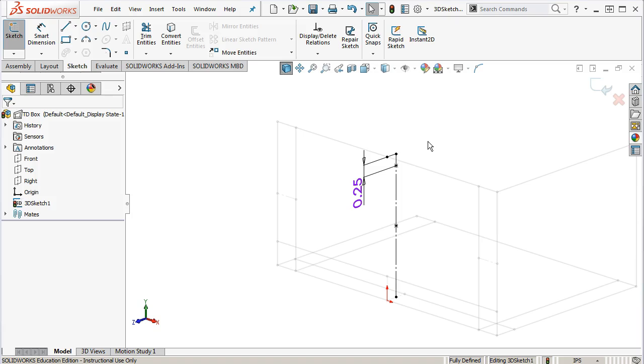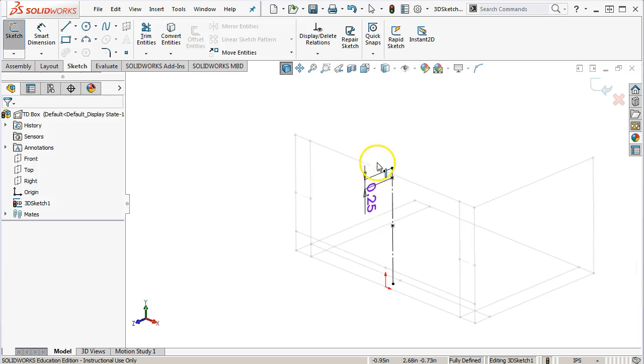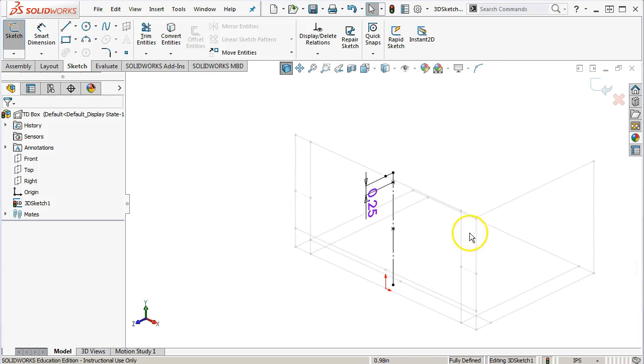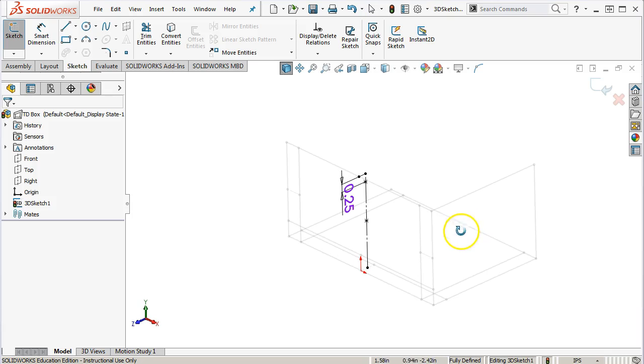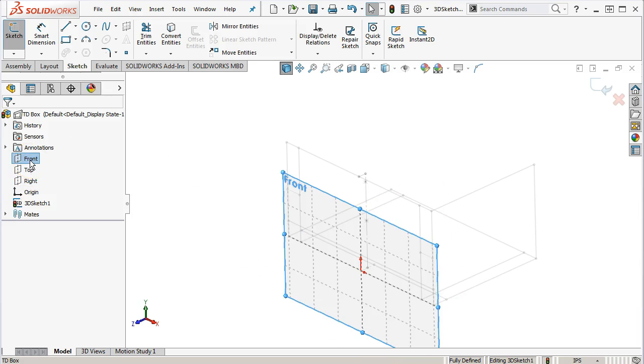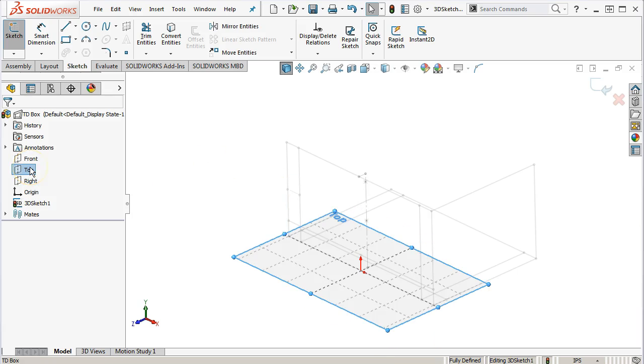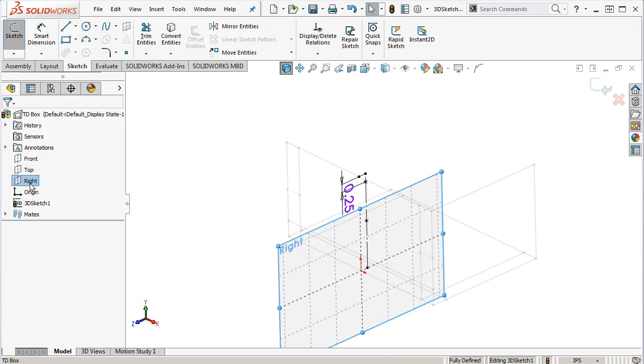Okay. Yes. So in the layout, if I'm editing the layout, how do I toggle from the front plane to, say, the right plane? Okay, so any of the 3D sketches, any of the layouts, when you want to toggle the 2D sketch, I click out, and then you double click on the front plane. You can double click in the work area, or I believe you can just double click the next plane.